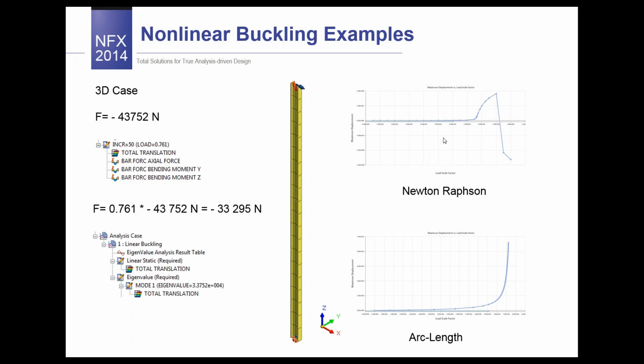So for this type of problem, we see that Newton-Raphson can be not stable, but there are several reasons for that. It's not only that Newton-Raphson is not stable itself, but there are other causes and other assumptions, especially because we are using a simple beam which has a perfect shape, and the load has been applied in the perfect way, oriented perfectly normal to the cross section.